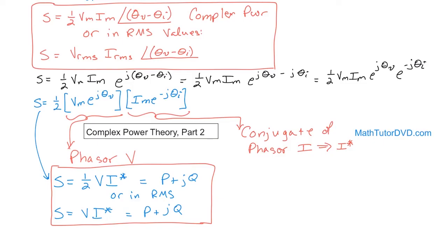You can dig back through all the notes and find the formula for P and Q and try to calculate all these things manually. But this makes it incredibly simple. All it's saying is, you solve the circuit, you find the voltage and the current going through that resistor, and you're going to be doing it in terms of phasors. So you'll know the phasor voltage V as a complex number, and you'll know the phasor current as a complex number.